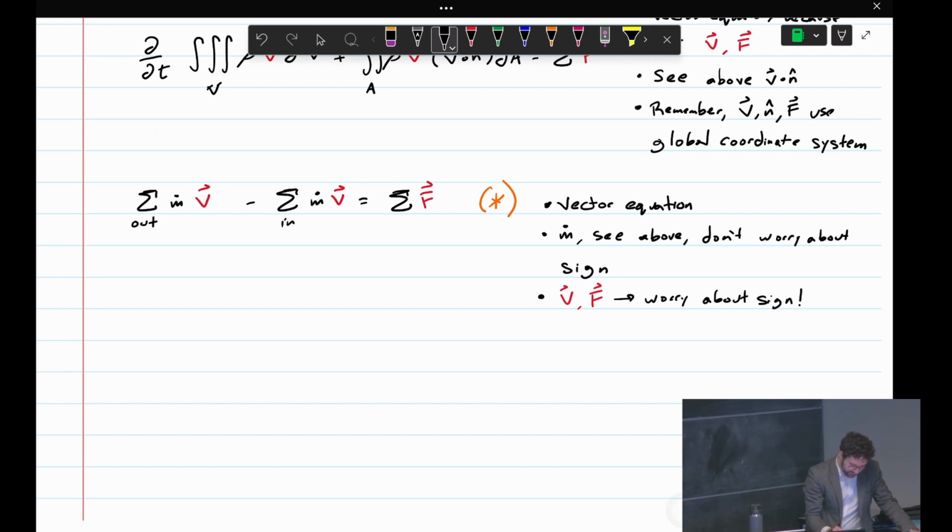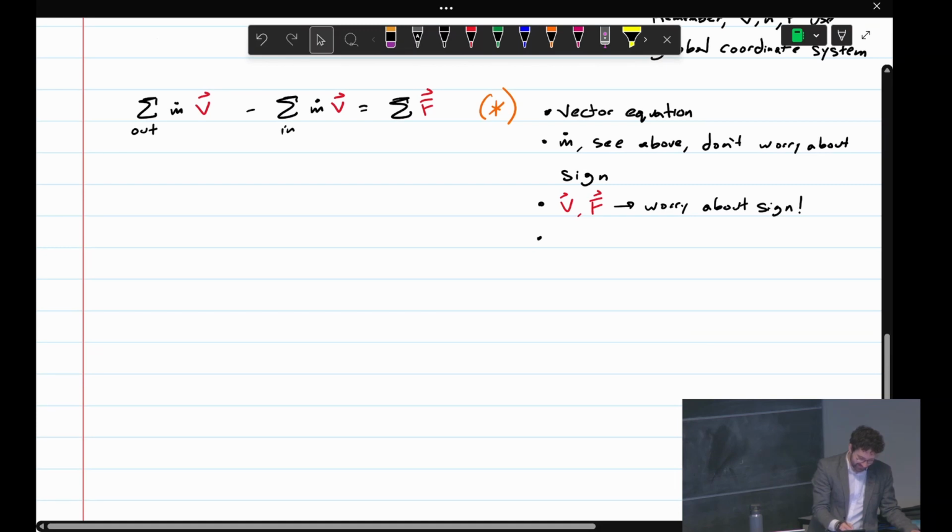That's a common error, a sign error in the v's. So if you have an inlet that's in the negative x direction, this whole thing would be negative, so you get negative, negative there. So just use the equation as it's written and be really careful about the signs on anything that's a vector. It sounds simple, but there are a lot of mistakes being made about this.